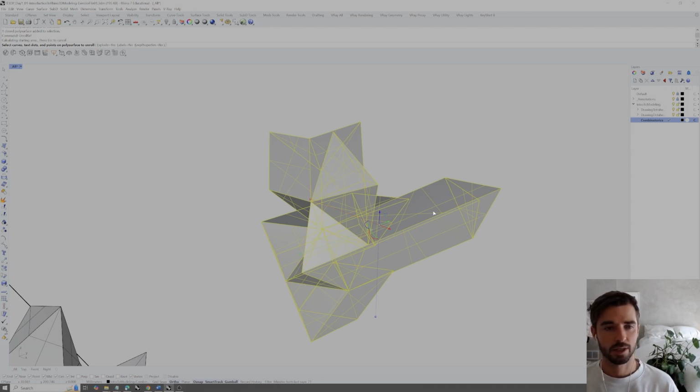Where they are guaranteed to be singly curved, meaning they can be unrolled using these unroll operations. The reason why unroll surface does not apply to doubly curved surface geometries is because they actually require distortion to unwrap. Think of any sheet of paper. If you try and bend that sheet of paper on two axes, it's going to wrinkle. It doesn't do a good job.